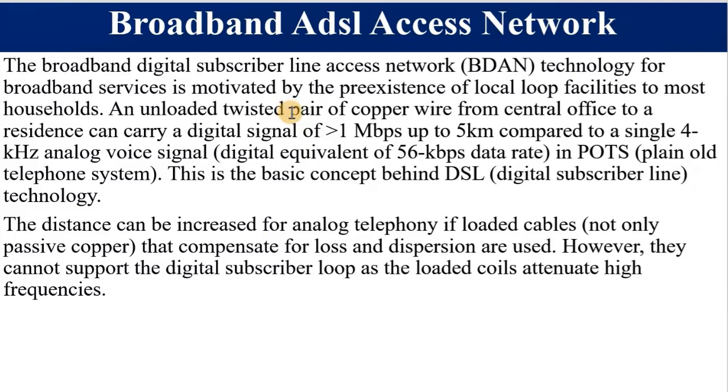So for ADSL to operate, these inductors that would have been put along a line, the process called loading, must be removed, or else ADSL will not operate. The distance can be increased for an analog telephone line for voice alone if we load cables. This helps to compensate for loss and dispersion.